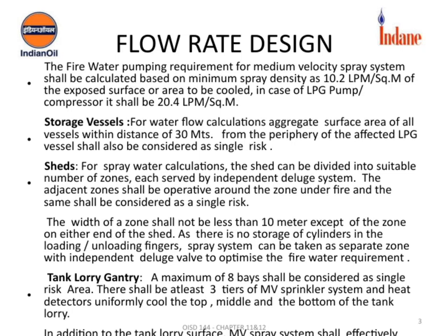Let's delve into the fire water pumping requirements as outlined in OISD 144, chapters 11 and 12. When designing the medium velocity spray system, we base the water flow calculations on a minimum spray density of 10.2 liters per minute per square meter of the exposed surface or area to be cooled. Now, for LPG pumps or compressors, this density doubles to 20.4 liters per minute per square meter, reflecting the higher risk involved.